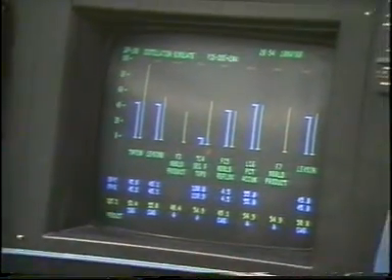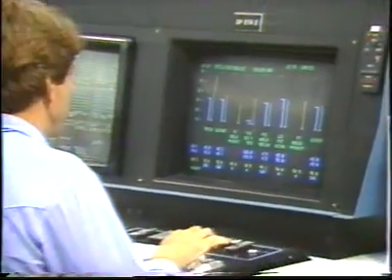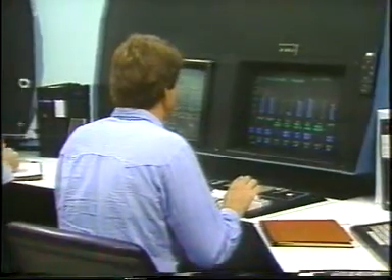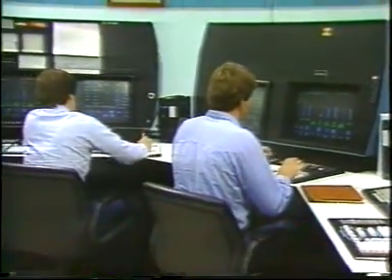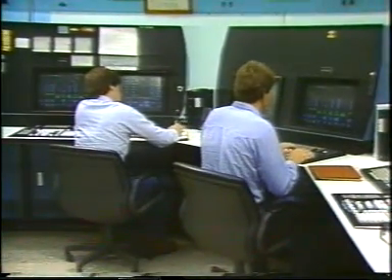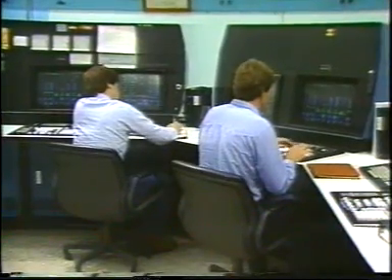Setting specifications for products allows us to control the type or range of molecules that are included in any one product. This is important because the properties of a distillation product, such as its boiling range, purity, color, or flammability, are determined by the type of molecules that are present in it. When a product is off specification, a change in tower operations must be made to change the composition of the product and bring it back on spec. This is usually done by adjusting the heat balance inside a column.